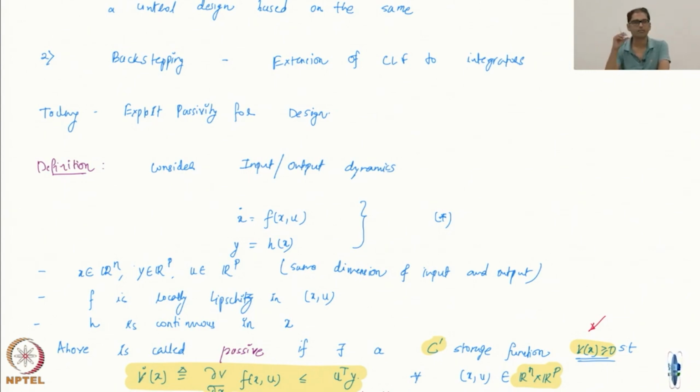This is somehow systems having some intrinsic good property. Until now, we have not assumed anything but the strict feedback structure and all that, which is not such a very stringent assumption. Honestly, most systems have this kind of structure. Because if they don't, then life is really, really hard for you. Realistically, you will find that this sort of strict feedback form is there.